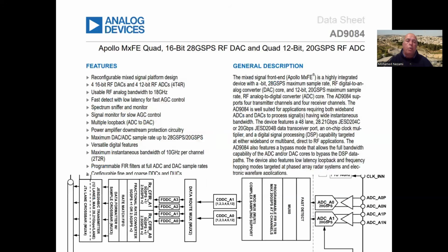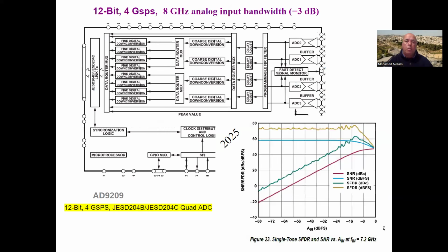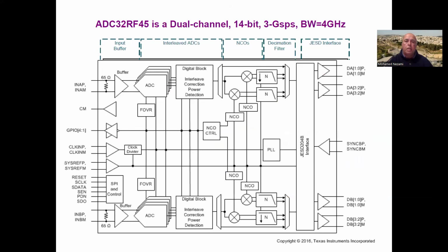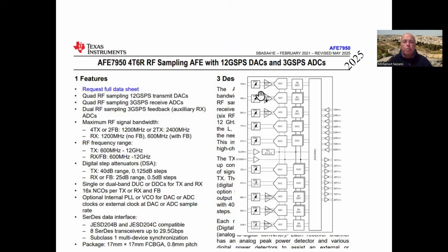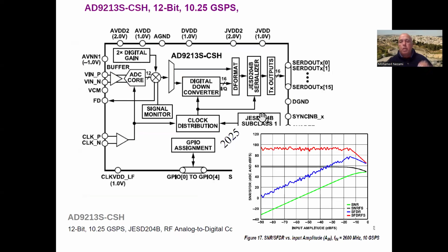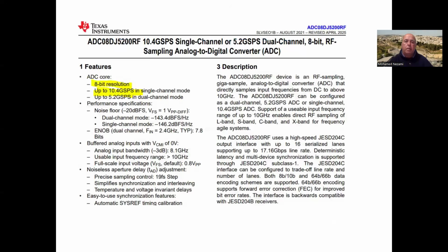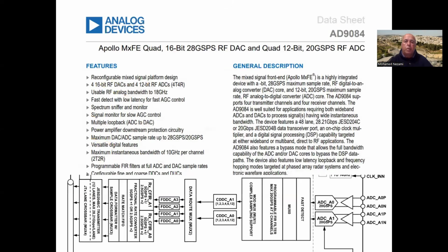When those creep into the signal and you start rotating the frequency, we have to keep track of them, because some of them will go around an alias and come right back in band. So there's a frequency planning aspect to this, and there are some spreadsheet calculators you can utilize to do the frequency planning, and we'll look at that next week.